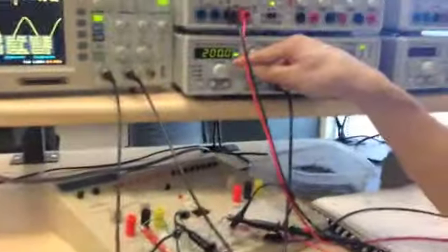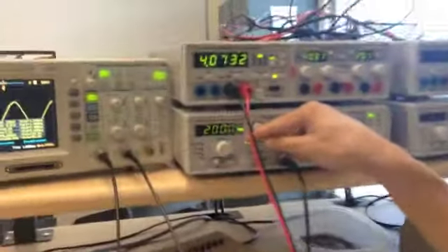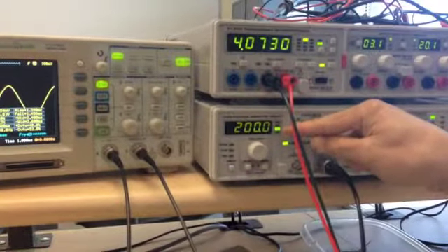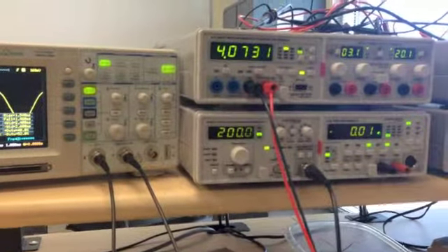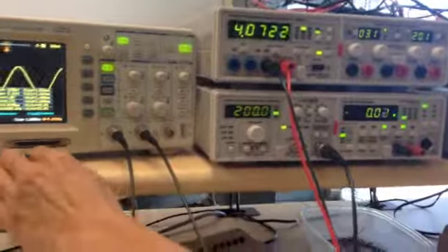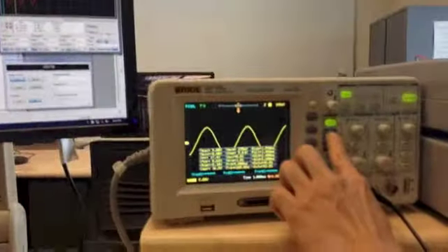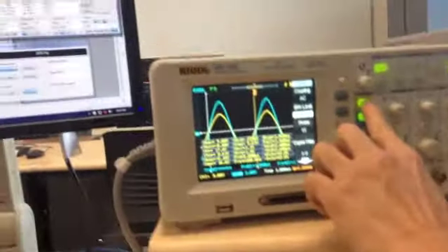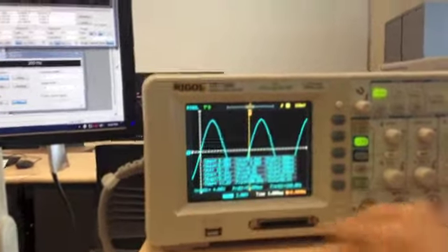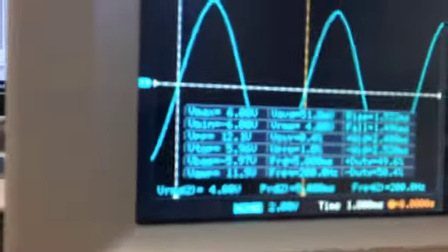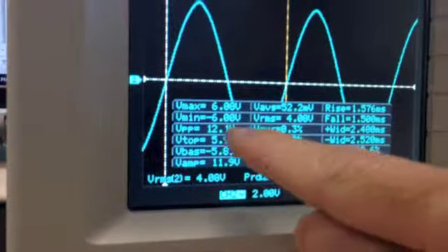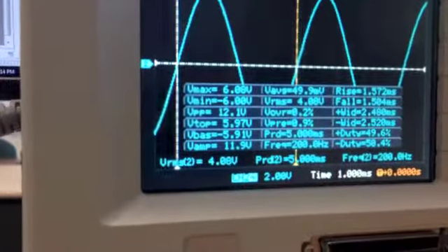Input still on, frequency still on 200 hertz. Come over here on the oscilloscope reading measurement on channel. I'm going to switch to channel 2. Turn on to channel 1. So my oscilloscope reading for the peak-to-peak voltage across R2 is 12.1 volts.